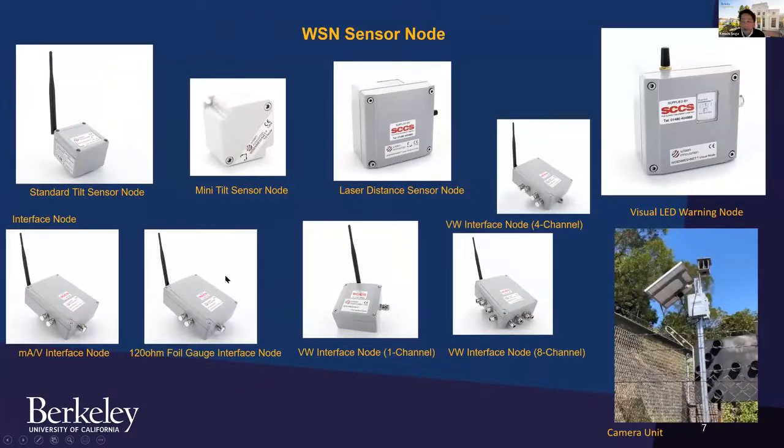Nowadays, and I'm sure you can get these in India as well, you have a variety of sensor systems that we use in practice that can be used in wireless mode. That means you can attach these to difficult-access sites. And so you can have a camera mode or vibrating wire string. These are conventional sensors attached to these wireless sensor systems.